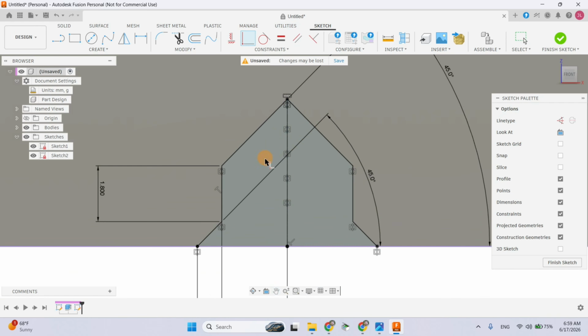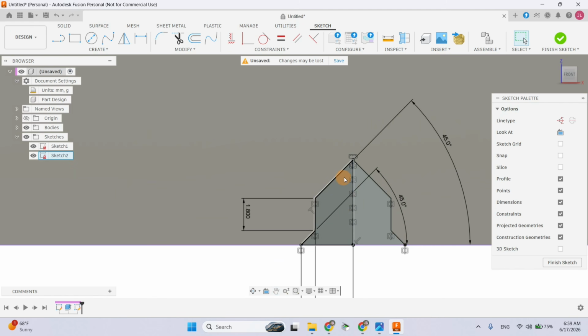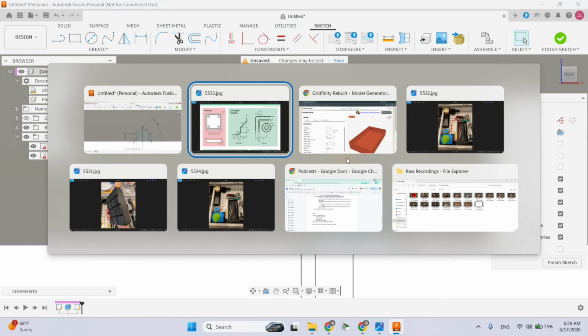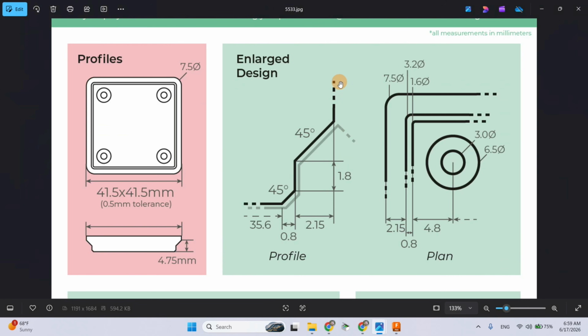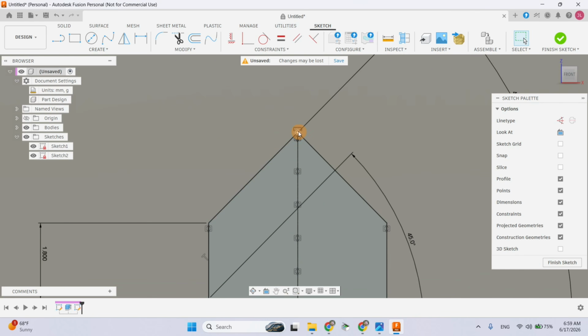Great. That's going to work a little better for our purposes now. And you'll see we'll build in that 0.5 millimeter tolerance when we cut this geometry right here. The reason is this profile isn't showing everything up to the halfway point, and so we're just going to model it all the way up to the halfway point.